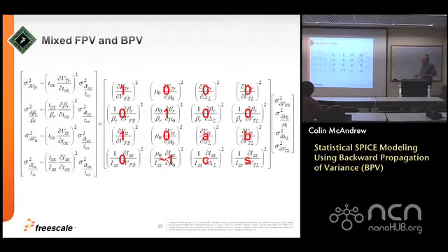Okay, and it turns out that in practice you can work out up front what many of these things should be. Here, this is the wide-long threshold voltage. It's not going to depend on mobility. It's not going to depend on delta L. It's not going to depend on, this is sort of an empirical variation in threshold for a short device. So that should be a 1. The beta of the wide-long transistor doesn't depend on threshold voltage. It should have a 1-to-1 relationship to mobility, which is that one there. It shouldn't depend on anything to do with short channel.